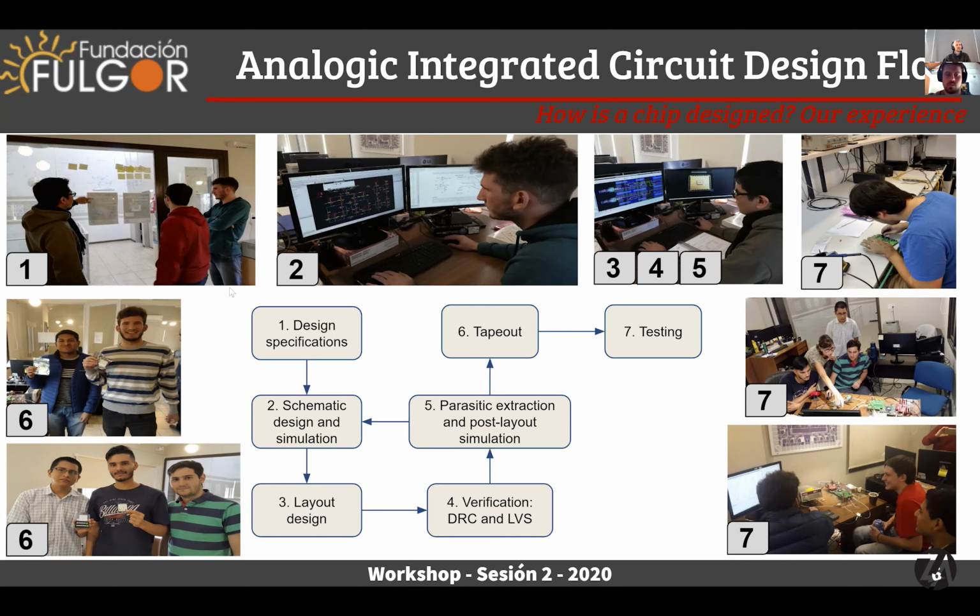Once we agree on the specifications, we do a schematic design and simulation at a schematic level. In this case, we use xschem for the schematic design and ngSpice for the simulations. Once we are good with the results, we move to the layout design.